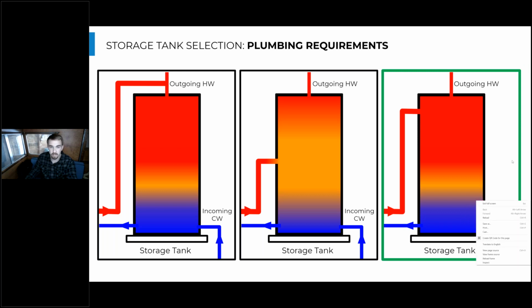We don't want that. So we have a high hot heat pump location, a cold low connection, and then dedicated entering and leaving water connections for the tank. So now our heat pump is separated from anything that's happening when it comes to water draws in the building. So it sees really consistent temperatures and flows as soon as its own pump turns on to draw from this tank.